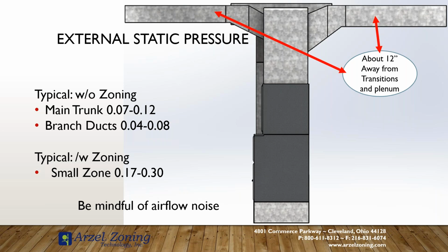And a lot of times what we run into residentially and commercially, it's not so much a problem of supply terminations, it's a problem of the duct that feeds those branches being inadequate to actually supply those branches, more often than not.